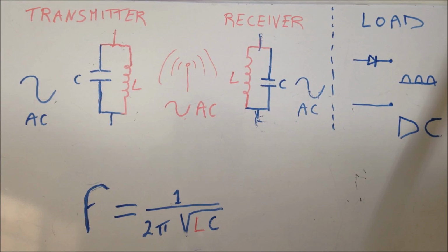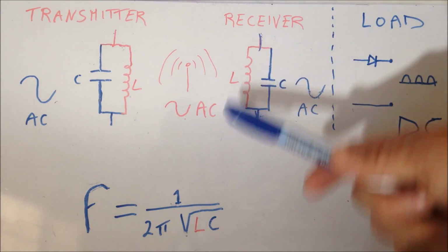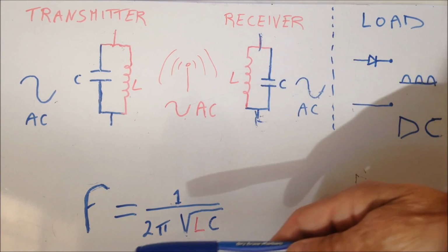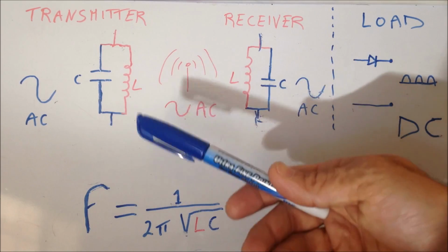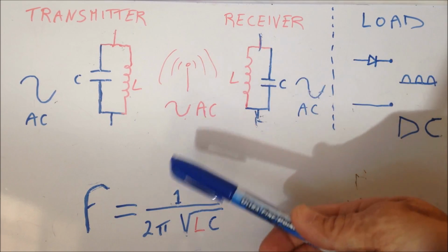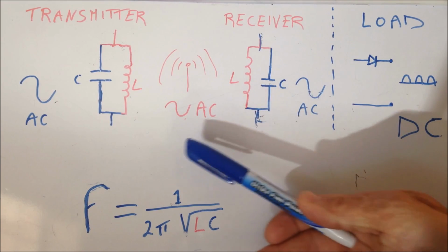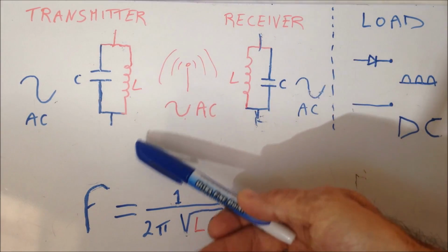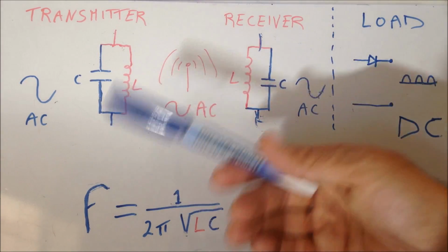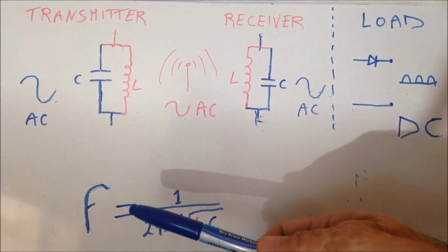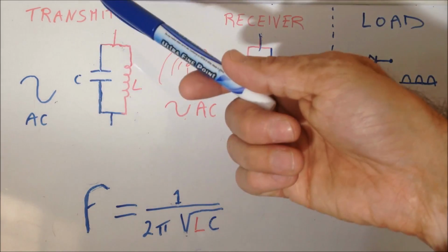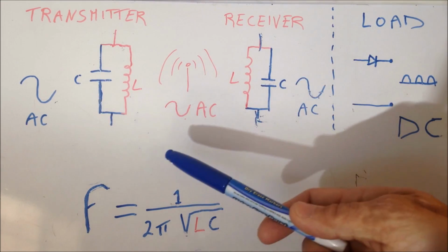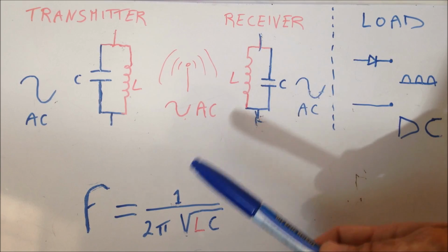Let's take a look at how we create some induction and wireless transmission. Of course, we need a transmitter and we need a receiver in order to create some resonance, and the resonance is what creates most of the electromagnetic field we have around. The most elementary circuit you can build is called a resonator, or simple LC tank circuit. It's very simple to make, and it's made out of a simple capacitance and an inductance. Our inductance is also commonly called an antenna.